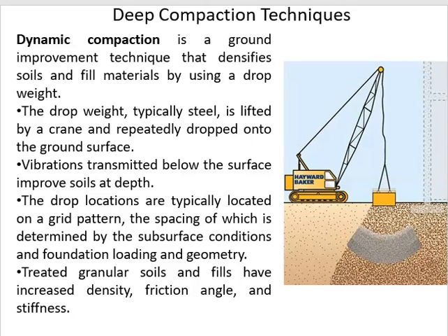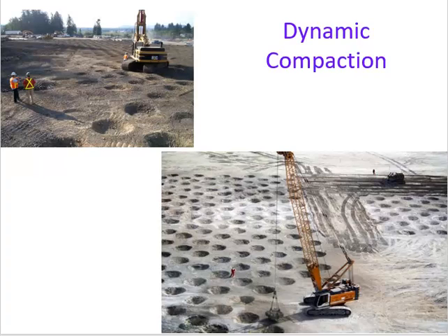This method is useful for machine foundations with impact loads. This method is effective up to a depth of 10 meter. The drop locations will be triangular or square grid pattern, the spacing of which is determined by the subsurface conditions.